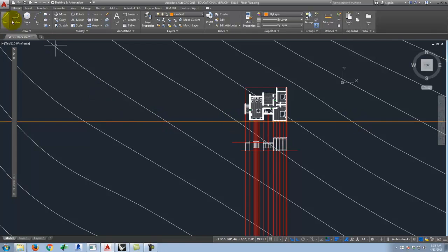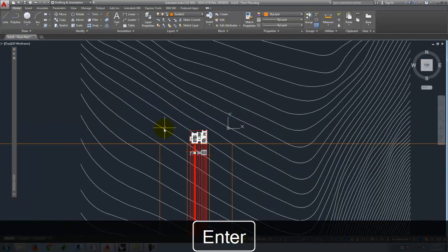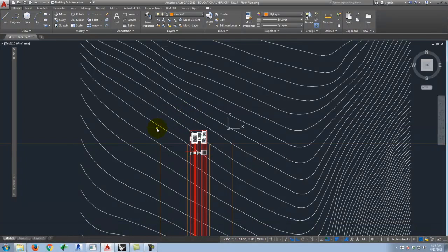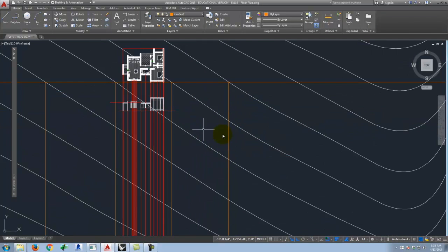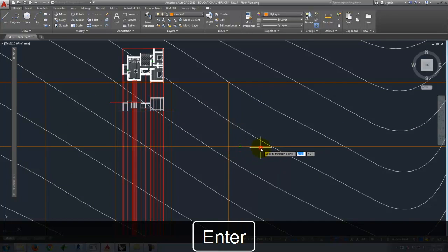Okay? So I'm going to go ahead and draw an array that starts at each of these points. So we'll go to there, we'll go to here, we'll go to here, and we'll go to here. Now, I told you guys last class what the difference in elevation was at each of these contours. Do you remember? 1 foot. It's 1 foot. Okay? So if I just started somewhere arbitrarily, let's just do another X line. And again, it doesn't matter, just somewhere arbitrarily.